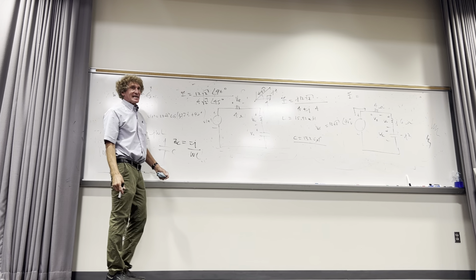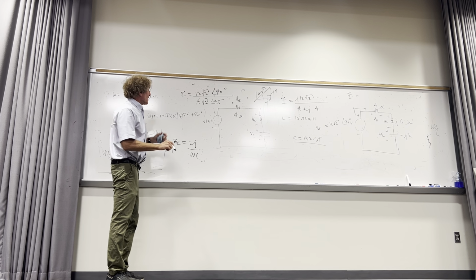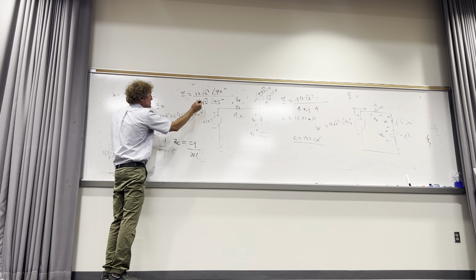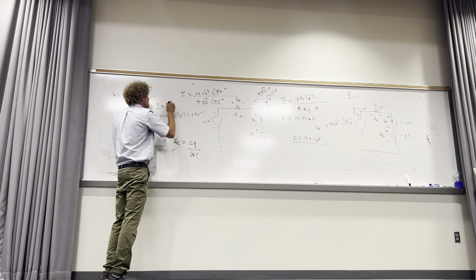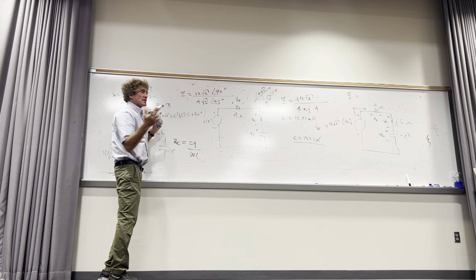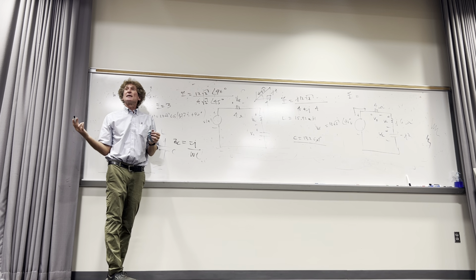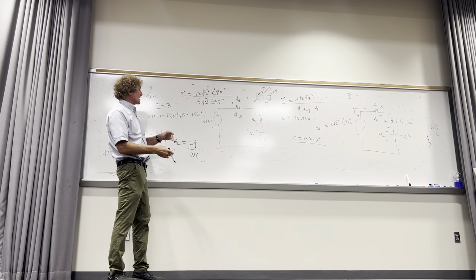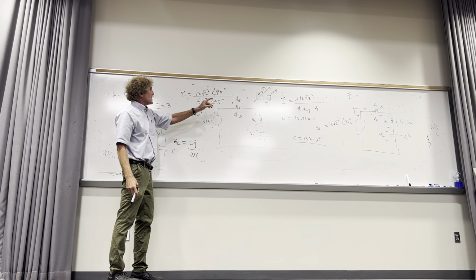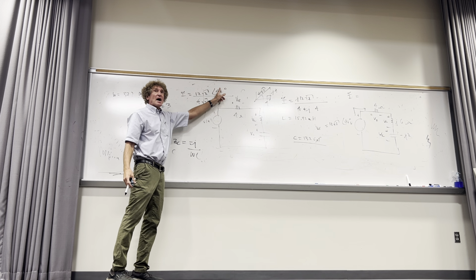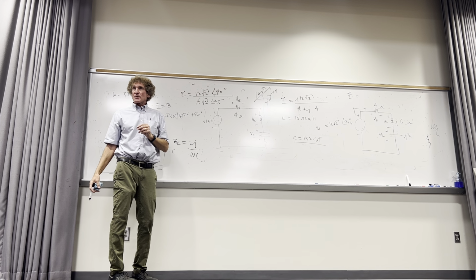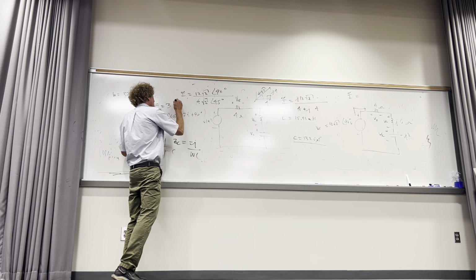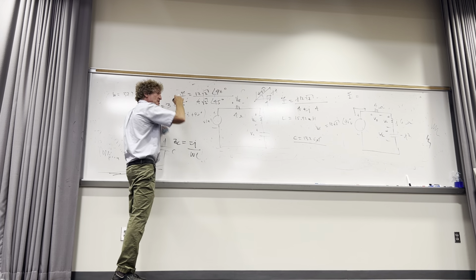Now, the only reason I did this is why? Well, that means my I phasor here is what? I got 12 divided by 4 is 3. The square roots of 2 kill each other, right? You all see this? Then I have 90, but when I take 45 from the denominator to the numerator, it's minus 45. So I'm left with simply 45 degrees. You all see this, class?